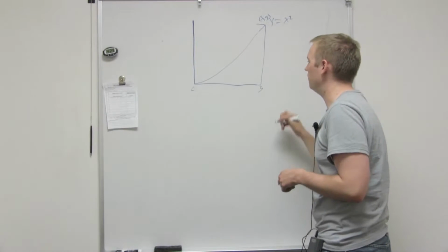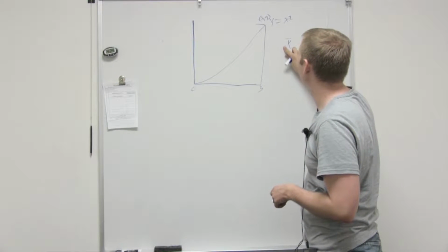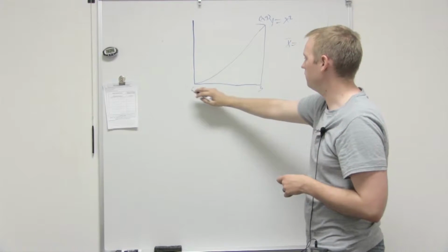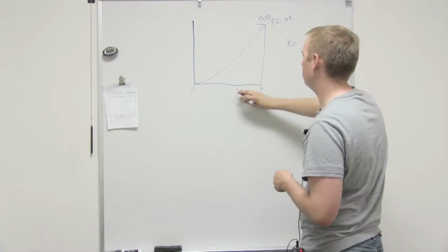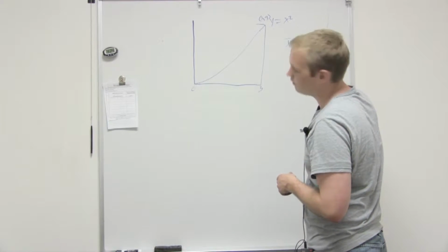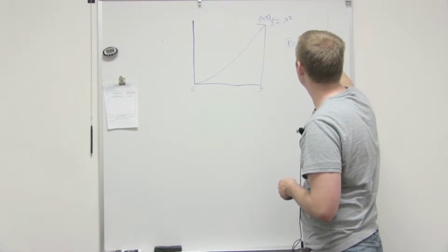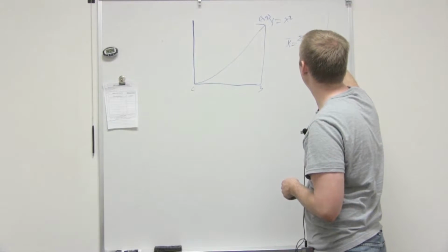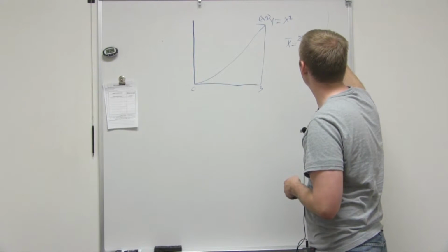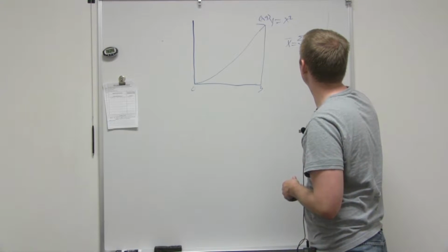And what are the basic equations that we have again? Solving for x bar first. x bar is the distance in the x direction to your centroid, which is the sum of x tilde times the area divided by the sum of the areas.